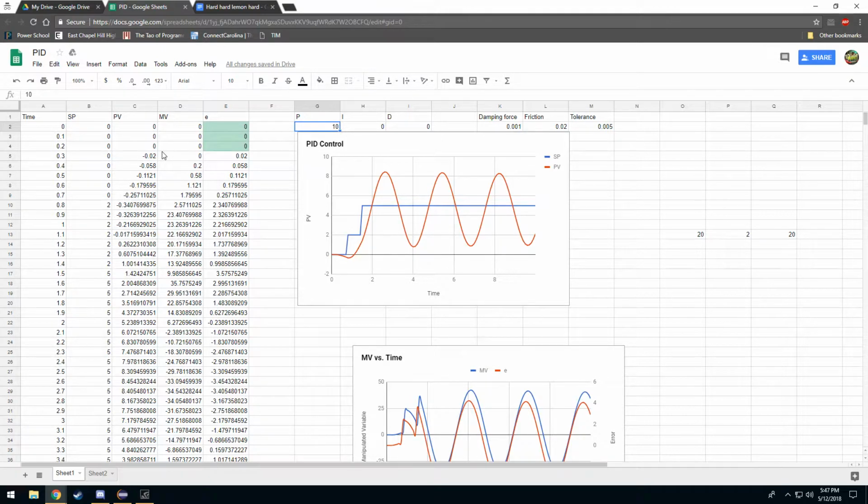You have a sensor on the elevator that'll tell you where exactly the intake is along the elevator, and you want to keep it at, let's say, 5 feet up, right? So the sensor says 5 feet. How are you going to do this? It's not like the motor will just auto hold there. Well, you're going to need to oscillate at that position. You want to put just the right amount of motor power to hold it at that position. So how are we going to do that?